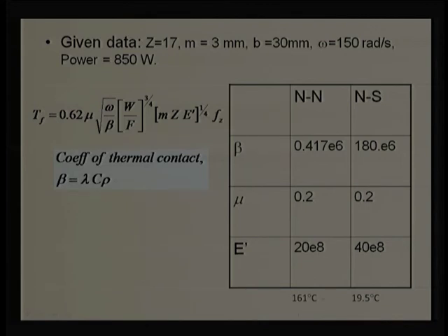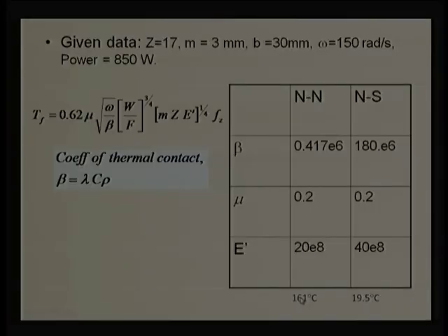When we operate the mixture, we do not operate more than 10 minutes, because if we operate continuously for 10 minutes, the temperature will continuously increase, and we may find that gear versus gear gets engaged, or there will be cold welding, it cannot be separated, cannot be rotated after that. That is the reason we want to keep operation for some time, not beyond a certain level, because there will be thermal instability, more flow and cold welding.